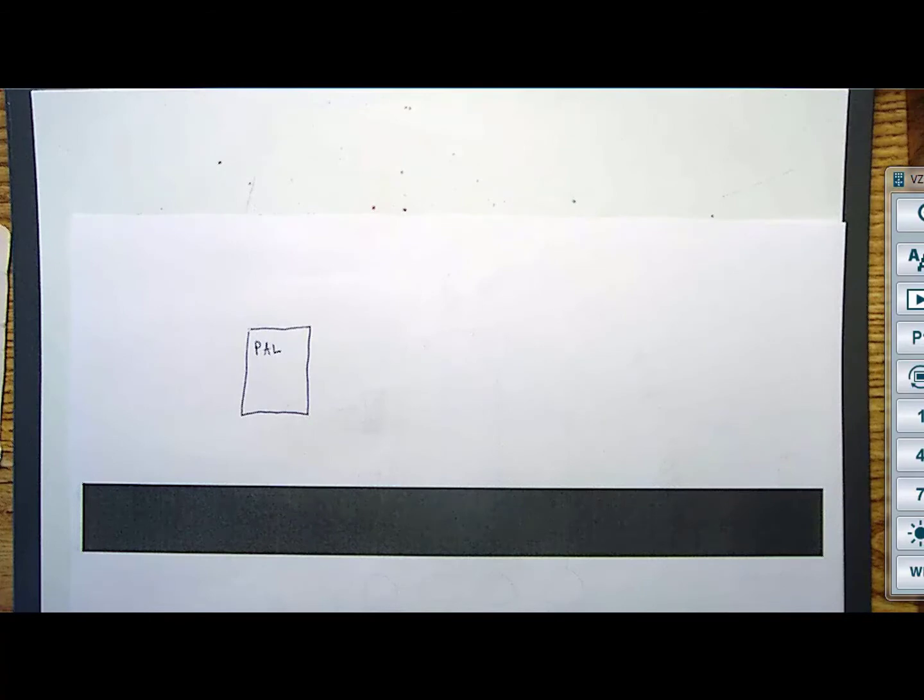But what do you think would make this even more useful if you had one chip? It would be to include the D flip-flop on here. Now, you don't want to hard code it so that it's always a D flip-flop. You'd like to be able to use it as a D flip-flop, but you'd also like to be able to use it as a combinational logic circuit, or you'd like the combinational logic to drive into the D input of the D flip-flop.